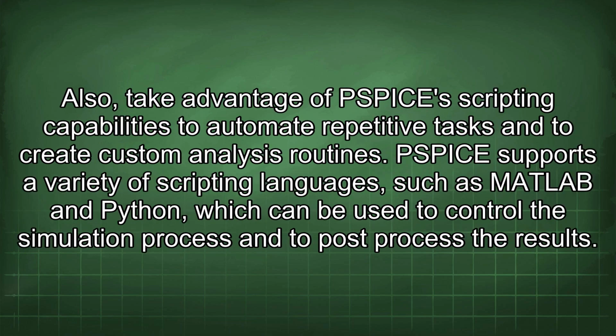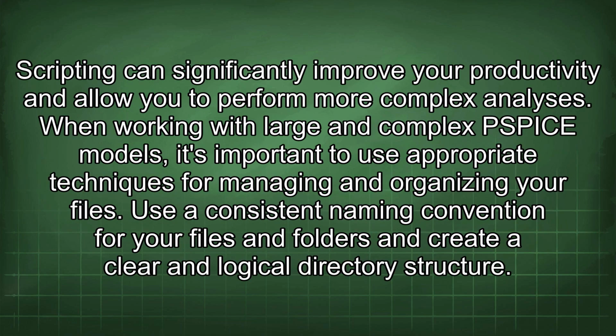Also, take advantage of PSPICE scripting capabilities to automate repetitive tasks and to create custom analysis routines. PSPICE supports a variety of scripting languages, such as MATLAB and Python, which can be used to control the simulation process and to post-process the results. Scripting can significantly improve your productivity and allow you to perform more complex analyses.